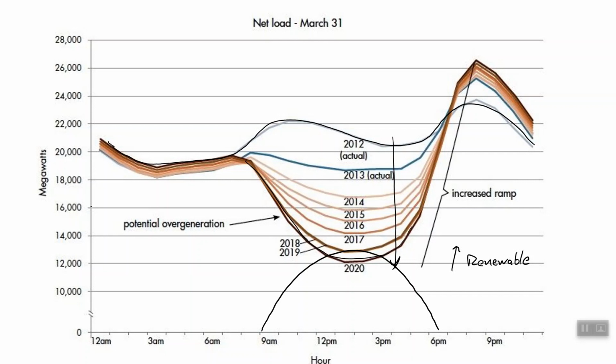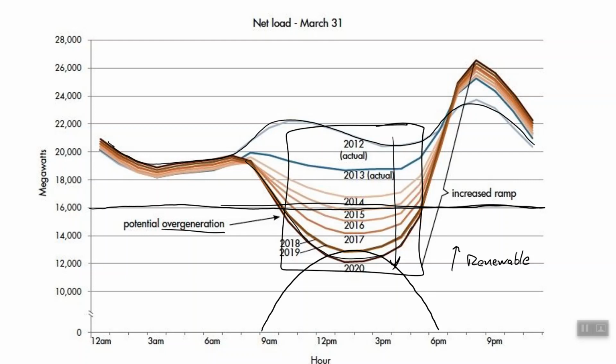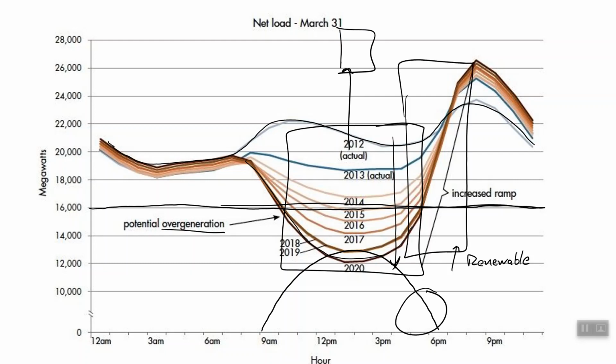Eventually we reach a point where, say this is the base load, we're going to drop below the base load, and we now have something called overgeneration, where we are making too much power, right? And so this, famously called the duck curve, shows how storage could be used here. So during these times when we have a high output of solar, we store that energy now in some storage medium. Then when solar drops off right here, but our demand increases significantly in the early afternoon, late evening,